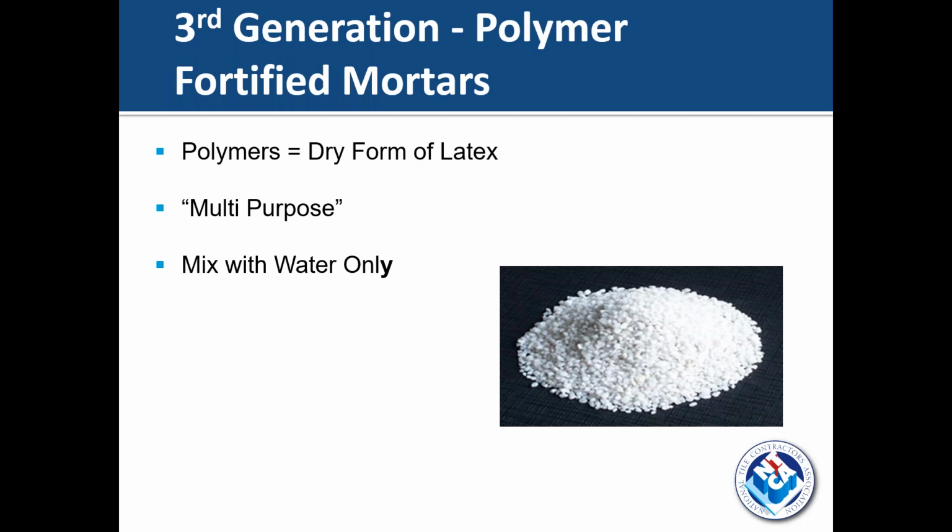Then the third generation was replacing the liquid additive with a dry form of latex. So now you buy a bag of thin set, a multi-purpose thin set, and there's no more mixing in of a liquid additive. It's mixed with the water only, and the latex is already contained within the product.